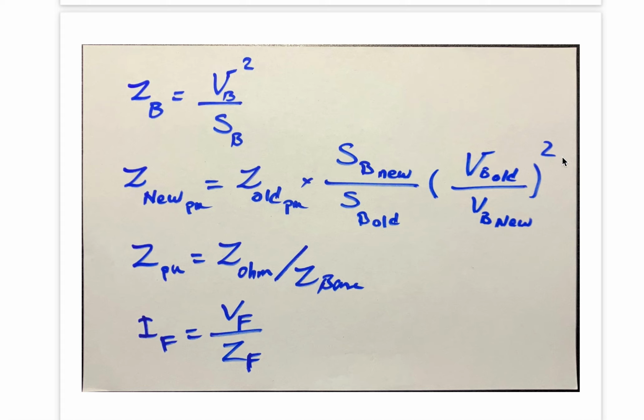Usually for the question about short circuit analysis, you don't need this last term. The rest is enough. But sometimes for a question which is only about transformers, when we give you the leakage reactance and ask what is the actual reactance on the high tension side, low tension side, and so on, you may need this one, in case the new voltage is different from the rating voltage of the transformer.